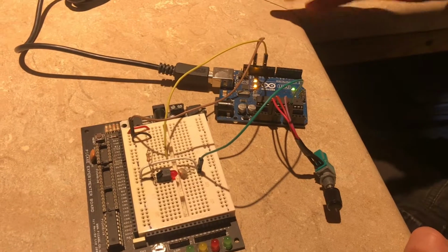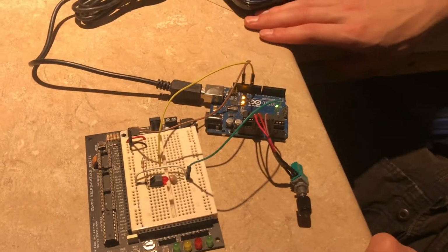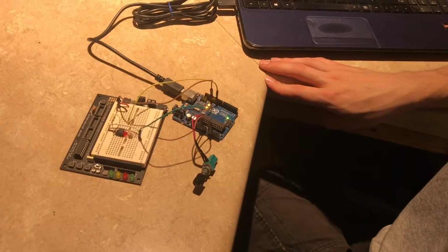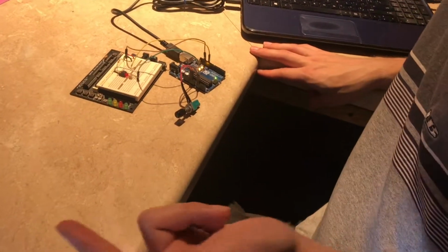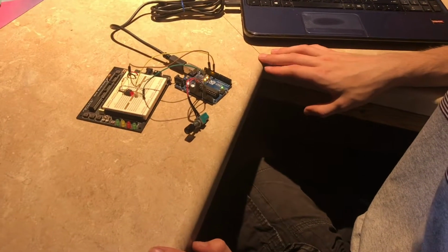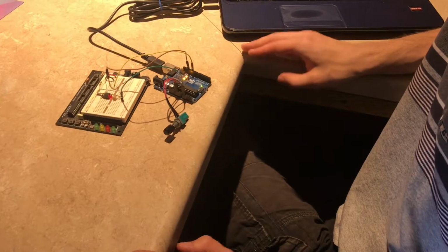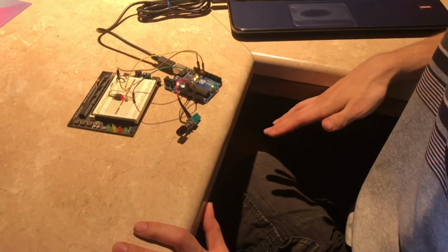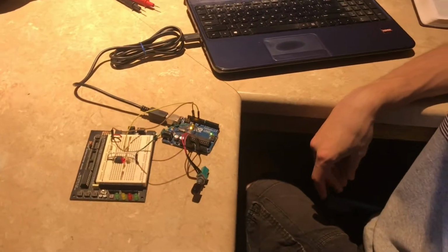Another would be, say, a thermostat in your house, or heating, trying to get a heater up to a certain temperature and staying at that temperature. So in that case, the output device is the heating coils. The sensor, the input device, you'd have to have a temperature sensor, and then the set point would be like 300 degrees or something. And in that system, if you were to throw ice on the heater, then the temperature would begin to drop, and the system would automatically increase the power to the coils so that it would bring it back up to the set point.